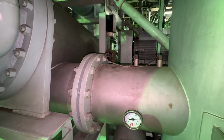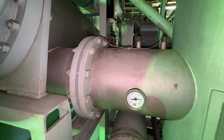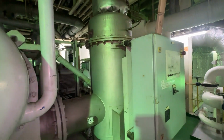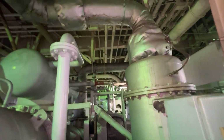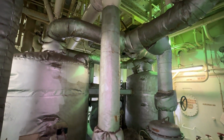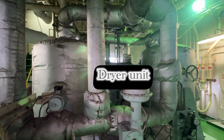This IG then will pass to the demister where the remaining water will be removed, and only cold IG will pass to the dryer. And this is how the demister looks. And from the demister, the IG through the pipeline will pass to the dryer unit, and this is the dryer unit where the remaining moisture from the IG will be removed.